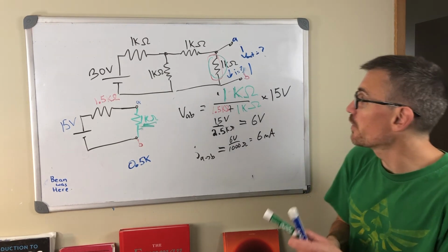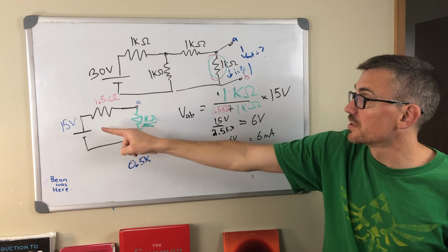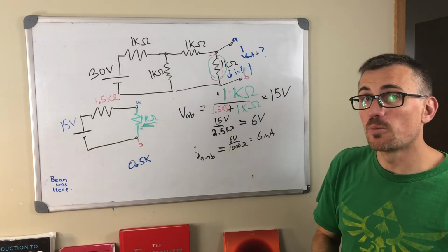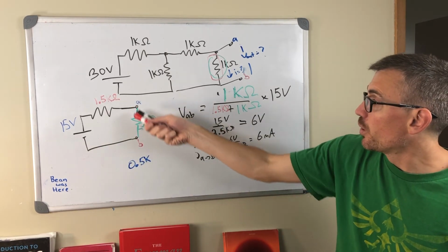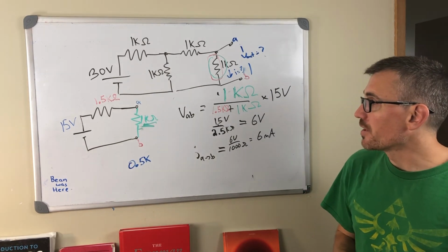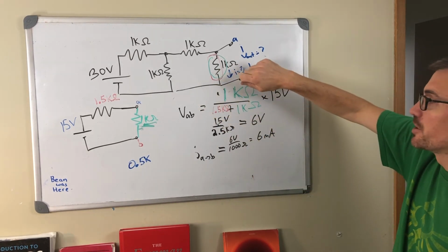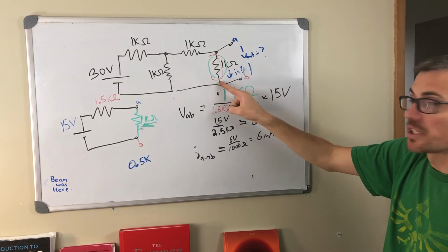And we're done. So we found the Thevenin equivalent circuit of this thing is a 15 volt V Thevenin and a 1.5 kilo ohm R Thevenin, and therefore we know the voltage drop across here. The beauty and the power of the Thevenin method is now we know what we'd get if we plugged a bunch of different things in here. If we had a potentiometer, what if we accidentally shorted it out, for example?